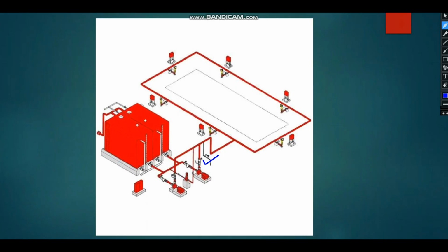So that is going to that side, and coming to the other side, here we have the connection which is going to the fire hydrant. This is the building located here. Surrounding this building, we completely have the fire hydrants placed at different distances, which we will see now. After that we have the fire hydrant box or fire hose cabinet. This is for the connection during a fire event. So this is the combined system riser.